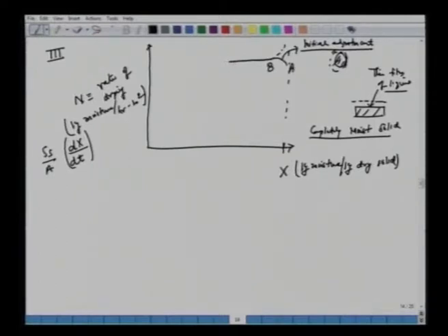Now the rate is constant till we hit the region which we called earlier the falling rate curve. Let's mark this region as C, because xc we will call the critical moisture content. This represents kg of moisture per kg of solid.